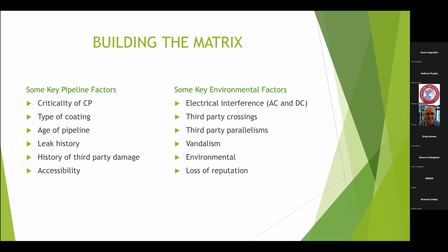If there's a history of third-party damage through vandalism, or in some countries, luckily not much in this country, you get hot taps on the pipes where people take the product, usually oil, or sometimes even they do hot taps for water in some Middle East countries. And of course, if the pipe's in a location where the access is difficult, say it's running under the M25 or running under motorways or canals or rivers, then you might rate that a little bit higher.